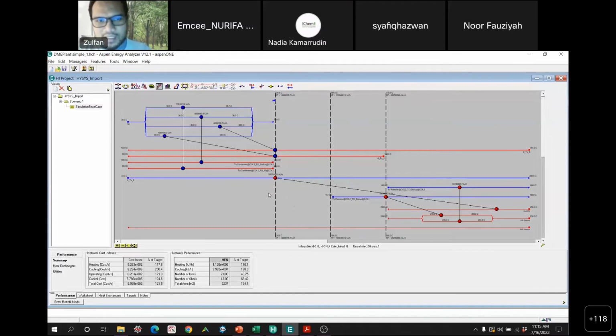Yeah, the existing heat exchangers, and as you can see over here, this is the pinch temperature. You can see that this stream is exchanging heat from the region below the pinch to the region above the pinch, because this hot oil is all the way on the right part of the pinch. This is the pinch point.